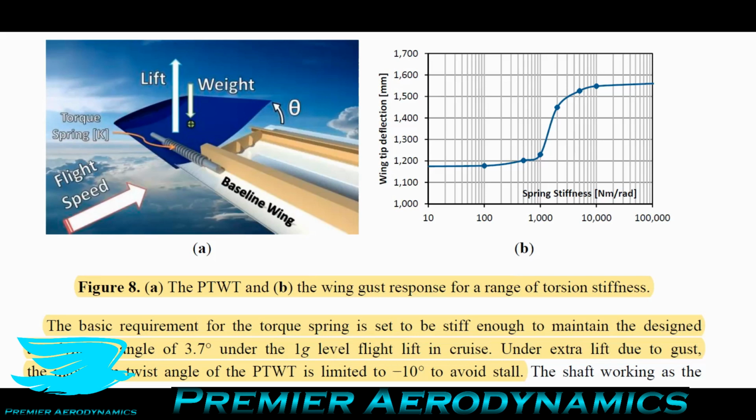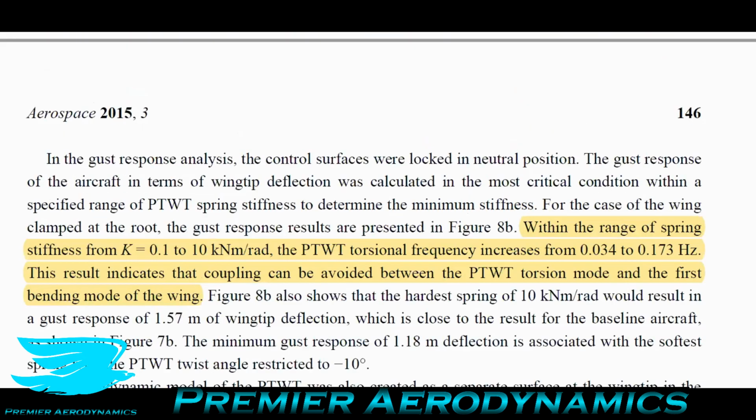If you have stall, then that's going to produce a massive loss in force, and that's going to result in the wing all of a sudden popping up, and that's going to be very hard to control, not to mention very dangerous, because then you're potentially overloading the wing, and then the wing will snap off and the pilot can't do anything about it because it was so sudden. And even if it was gradual, they still really couldn't do much because the wing is already overloaded and they don't have the flow control device to help it. So that's why you really want to stop this from happening, and that's why they made this spring very stiff. So it's a very clever design. I'm quite impressed. It's a little bit out of the box.